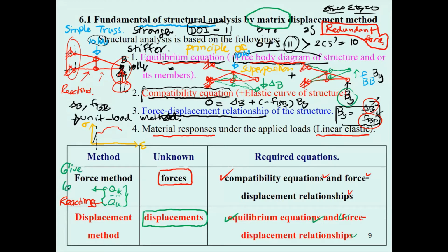I will give you the given loads that are tied to the structure, and this will be related to a spring. For the spring, force equals stiffness times displacement, so you will have this stiffness, and then this will come with the displacement matrix. One is going to be the unknown displacement, and another is going to be the known displacement. Why do you know the displacement? We know the displacement due to the support.